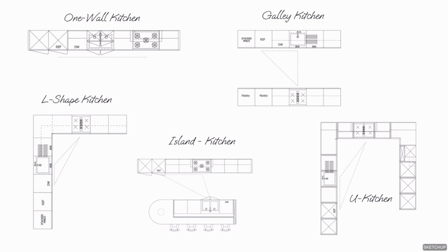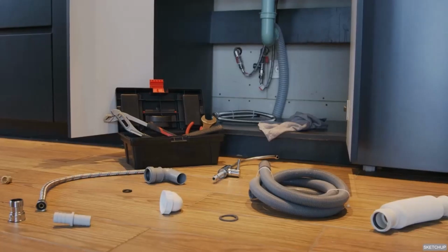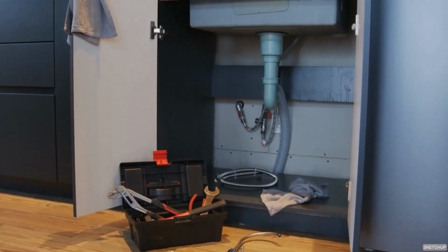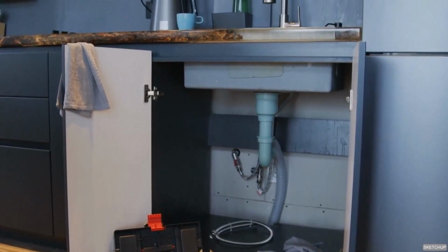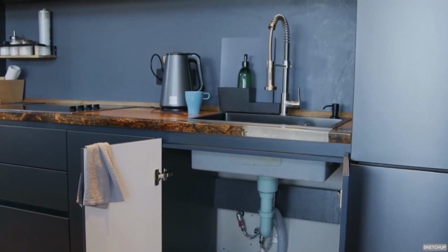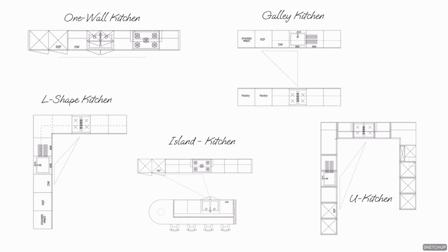It's crucial to commence by identifying the most suitable layout for your kitchen space for your client's needs. Keep in mind that the placement of electrical sockets, water outlets, and plumbing significantly influences the feasible layout. Budget constraints may limit the flexibility to relocate these elements, especially in the case of island kitchens where freshwater supply and plumbing must be situated within the floor.